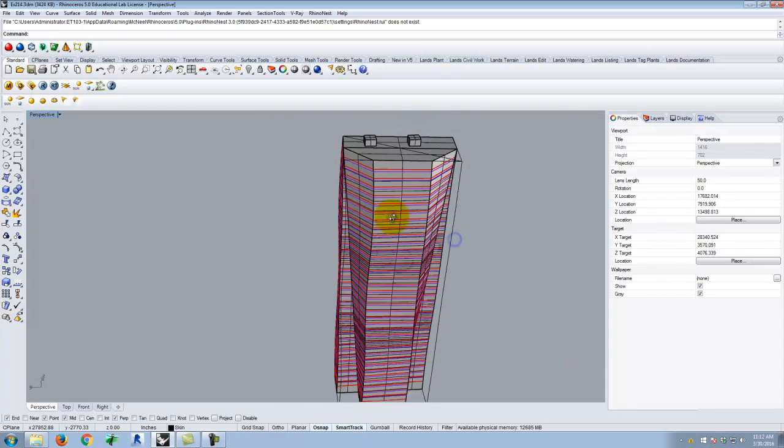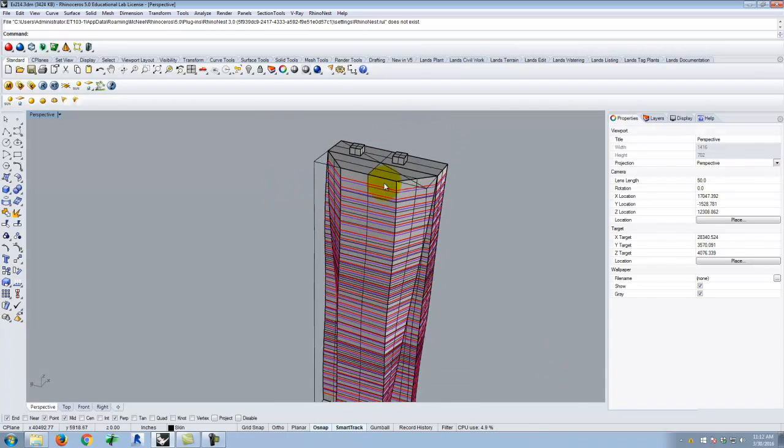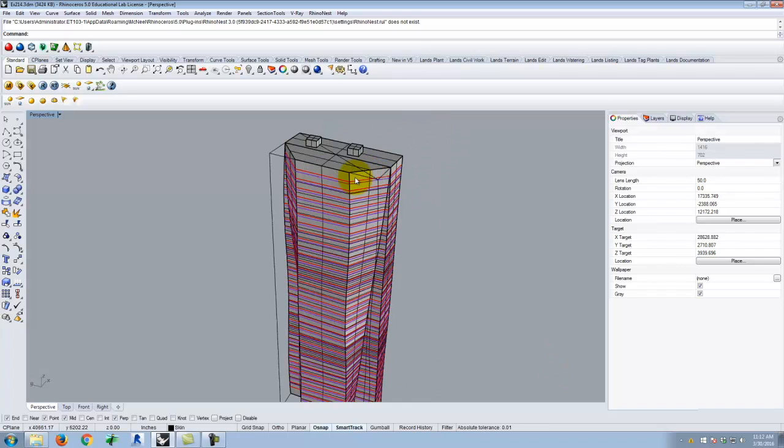If you have trouble with the unrolled surface, you can go back through and re-loft the surface together by creating some side curves, and each loft will therefore unroll because it's a straight line. That's the nature of a lofted surface.